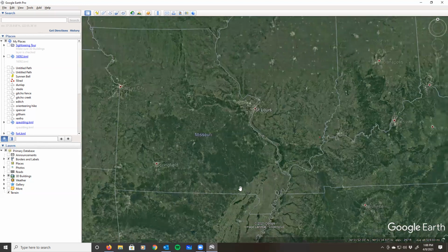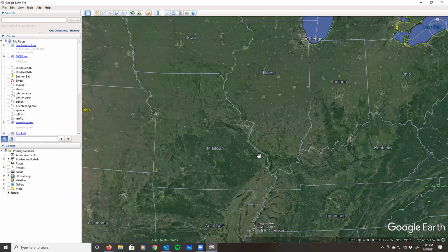So everything is defined from that point. Now, there's not a marker there or anything like that. It's basically a point on a map that says at this point, this is where our coordinate system starts from. Also, they say that it is set at 1 part on the central meridian. It's 1 part in 17,000 too small.